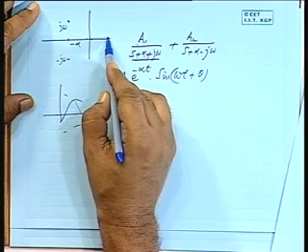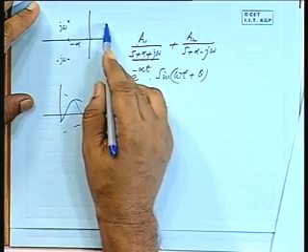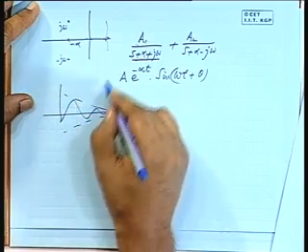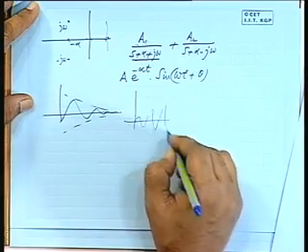Had alpha been here, that means if you have roots with the real part on the right hand side, then this will become e to the power plus alpha t and that will be causing a divergent oscillatory function, all right. So, it will keep on increasing. Can you have a situation when the current will keep on increasing and oscillatory when the voltage has been withdrawn? Again, that is not possible, it will be against the principle of conservation of energy.